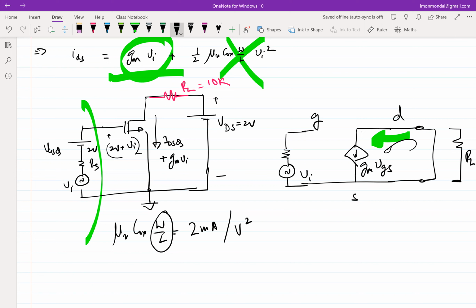Okay. So how do you get to the DC current? Under quiescent condition, right? When you change anything in the circuit, you have to go back to see whether your quiescent has gotten disturbed or not. If the quiescent has gotten disturbed, again your small signal model will get disturbed. So any change, go back to quiescent and check that your quiescent isn't disturbed. So now we have to check whether the quiescent has gotten disturbed or not. So how do I check? What am I looking for?